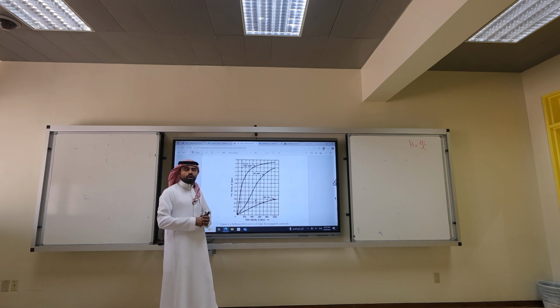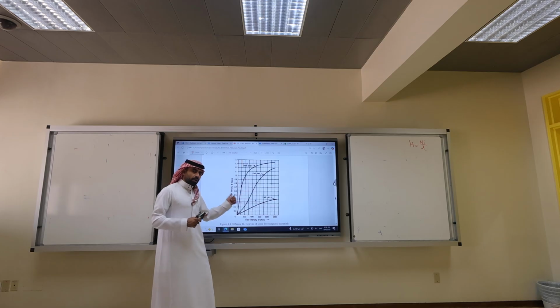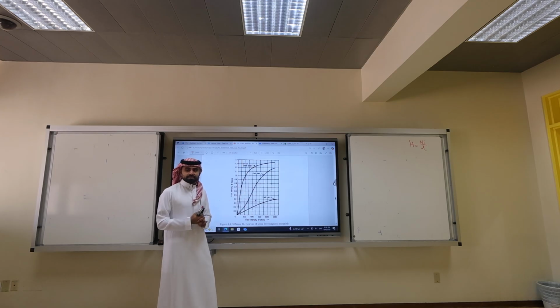When you buy a transformer, don't forget to ask for the B-H data. Otherwise, you cannot simulate it. You cannot do your math. And some of them lie in the data, as some of you lied in the lab. How do I know if it's true? You buy from a reputable manufacturer.